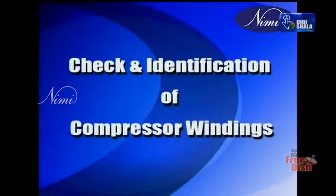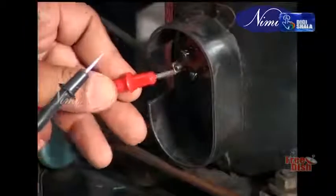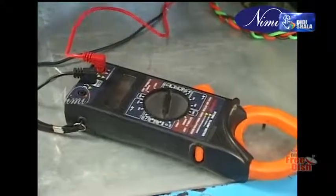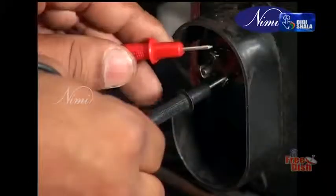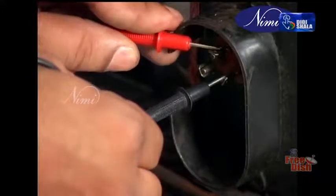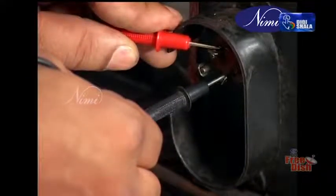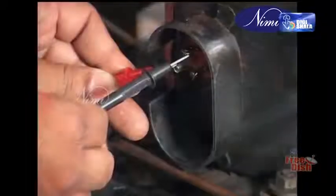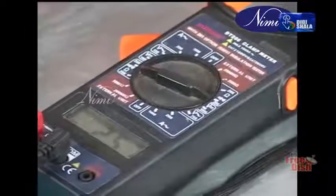Check and identification of compressor windings. Check the continuity between terminal pins of the compressor motor. After checking the resistance between these terminal pins, we found the running winding resistance is always less than the starting winding. Starting winding resistance is always higher than running winding.